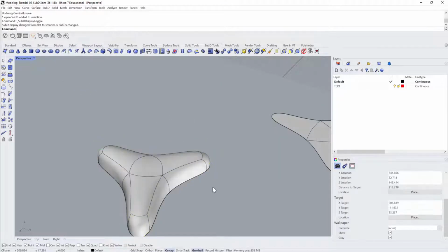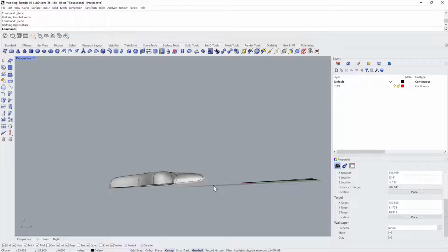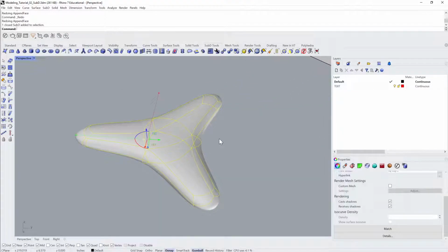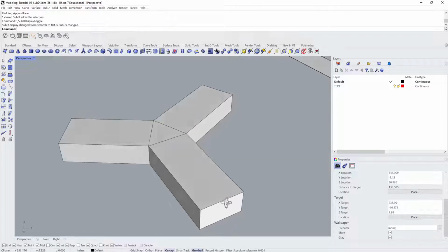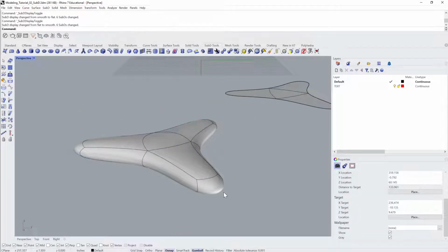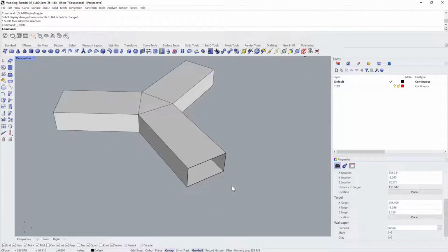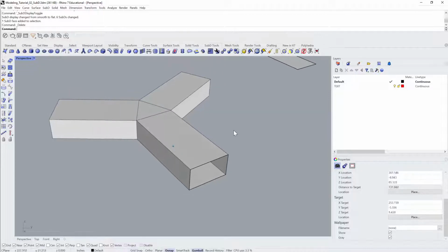By hitting the tab key, oops, went back too far. Let's enclose this surface. By hitting the tab key and filling in these end caps, you can see that curves everything here. But the geometry behaves very differently, and then to get rid of that face, I'm just Shift-Control selecting it and hitting the Delete key, so that's handy.